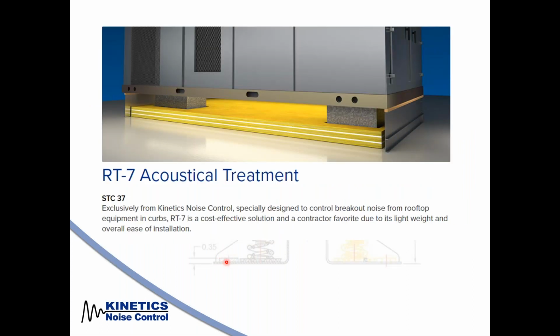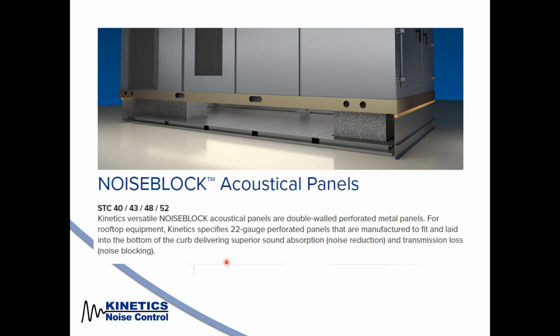For instance, you can go with our cheaper RT7 that gives you an STC rating up to 37. If that 37 is not high enough, you can jump into our NoiseBlock, which is our micro-perf sheet metal acoustical noise blocking panels that we use in our barrier wall system. This can lay in the bottom of the curb as well, and based on the different thicknesses available, you can get all the way up to an STC level of 52 with that one. So again, with the ESSR products, it's very much a design system based on the application and the noise requirements of the installation.